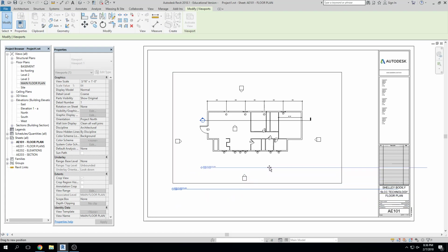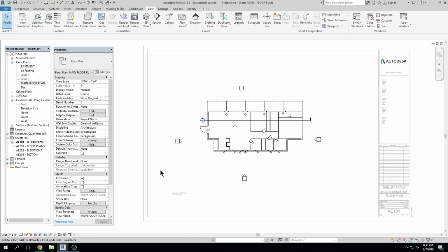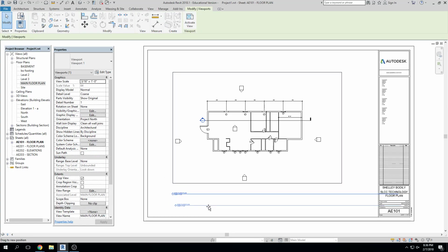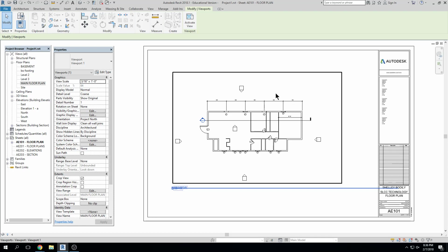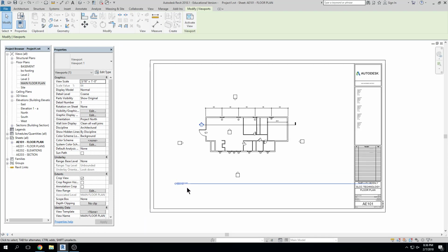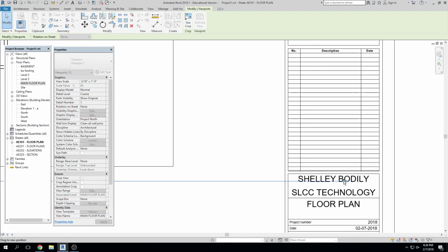And you'll notice that it starts to want to snap and line up with other things, okay? But if I double click on that, I engage the viewport. So, you know, if I click once I can hold and drag and move, okay. If I want to make this line shorter and make it a little bit more appropriate for this drawing, or I want to rename it, you know, the drawing like I did from here, I would first have to click on the viewport one time. And do you notice now this grip over here pops up? I can click and drag it in,